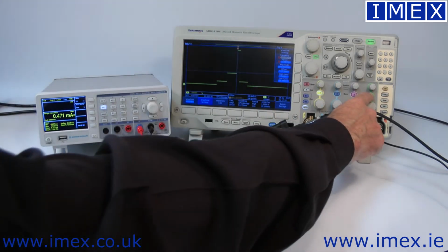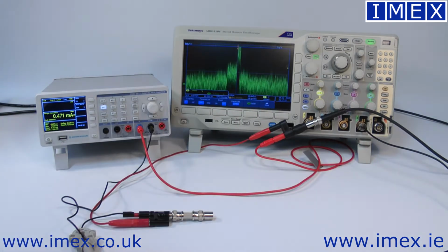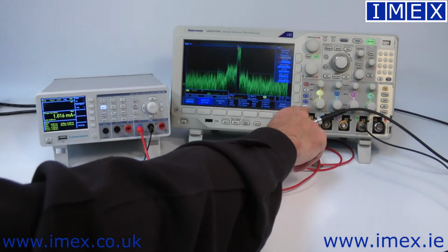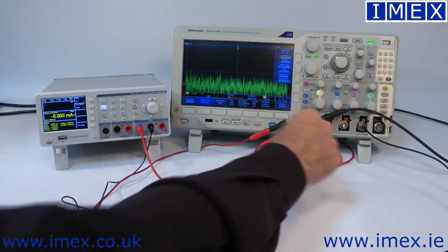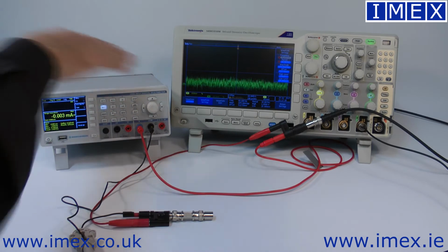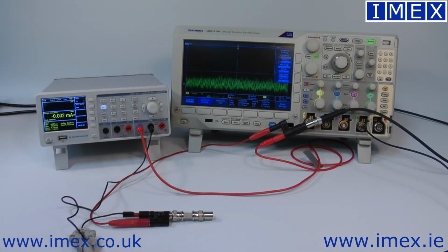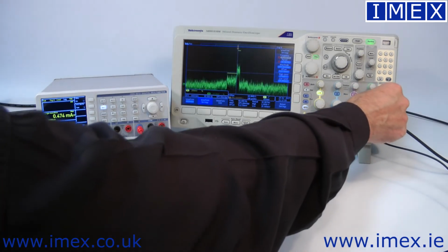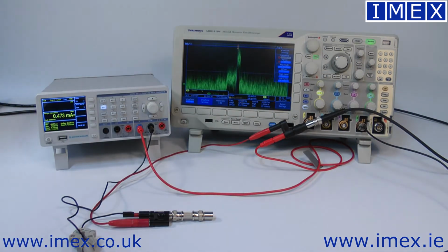Okay, so I have that set up on channel 4, and we've got a noisy waveform here. First, I should probably point out, if I turn off the AFG output, we now know there is zero signal or zero current there, and yet we still have a lot of noise around the zero line. For a current probe like this, the first step is to actually null out that zero, so you need to set it to 0 as best you can, and then we can make a sensible measurement. So we'll turn our AFG back on, or scale up. Okay. So as you can see, we've got a very noisy waveform.